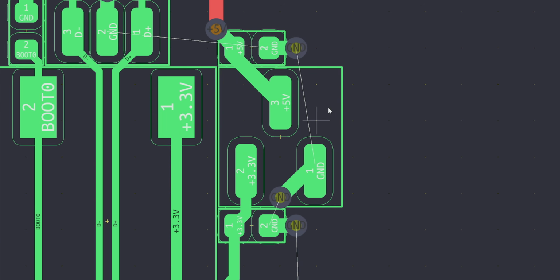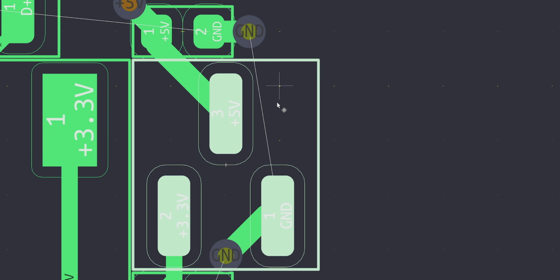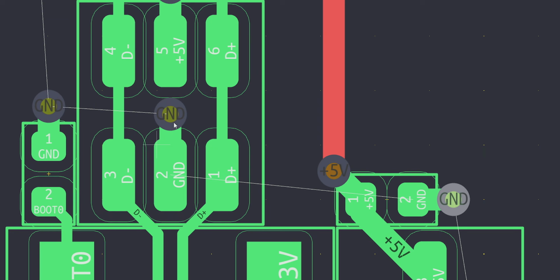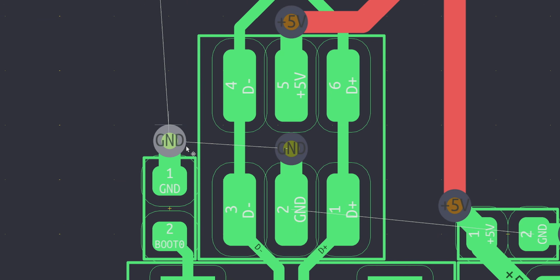Now, if we jump over here to the right, this is of course our voltage regulator. So we take our 5 volt in, we have our little stabilizing capacitor here, which is feeding to ground. You'll notice this pattern too on all these. I'm using these vias on ground here. And the reason for that is we're actually using a ground plane to ground everything out. It's a more standardized practice with PCBs.